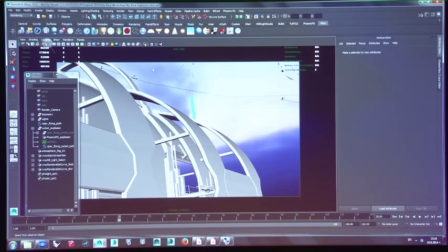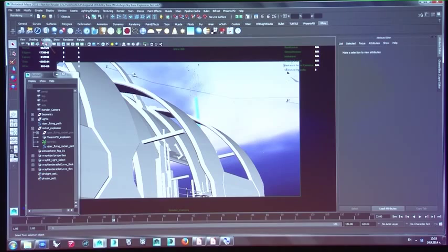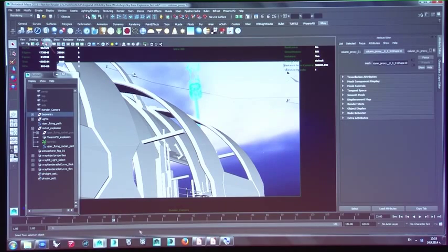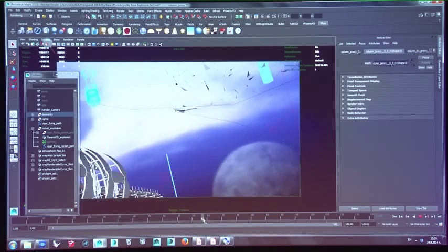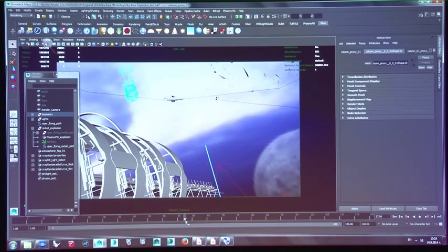Proxy is a way, for those of you who don't know, to cache geometry on the hard drive and not store it in the RAM memory of the computer for rendering, but read it directly from the hard drive. And this is a very memory efficient process in V-Ray. So for example, for these columns or whatever, spaceship columns floating in the air behind, I have created proxies since they are going to be far away from the camera. And I would like them because they are quite heavy.